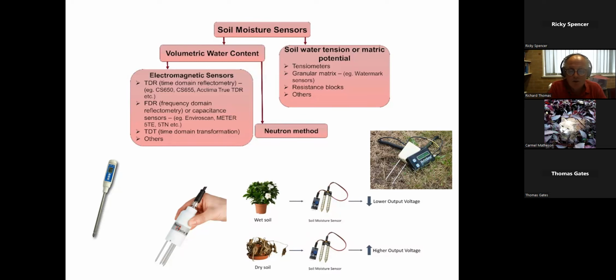We can measure in situ using sensors. These are really good, but they have to be calibrated. Don't just think you can go out into the soil, leave them there and forget about them forever. You do have to keep track that they are giving you sensible answers. Basically they're an electrode, and what they're doing is measuring the conductivity, because all groundwaters contain soluble ions.